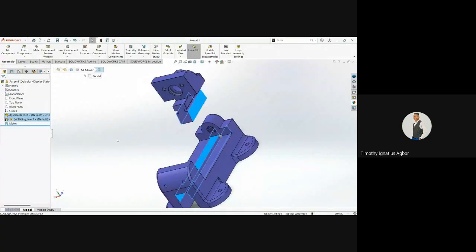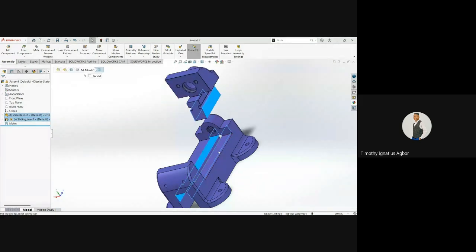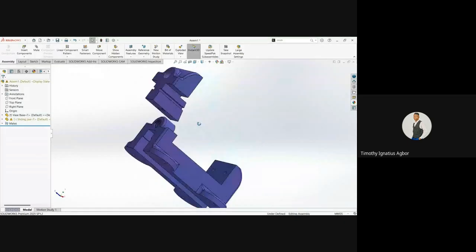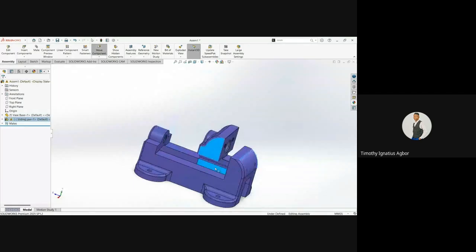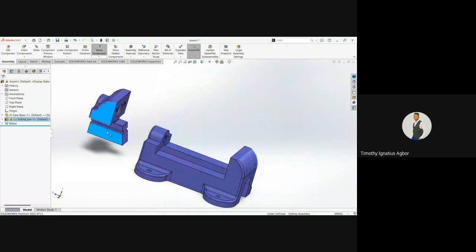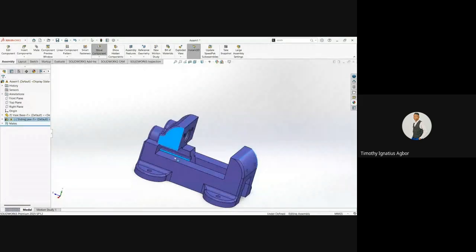We apply a mate. We click okay immediately and apply the mate. So it will make sure that this is at the center. So if I move this, anyhow I move it, it is always at the center of this. It's within this width. Did you get it?